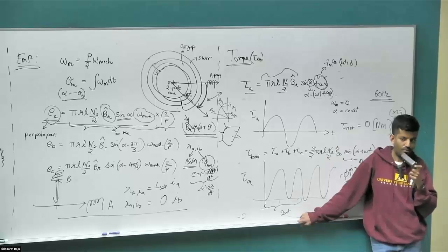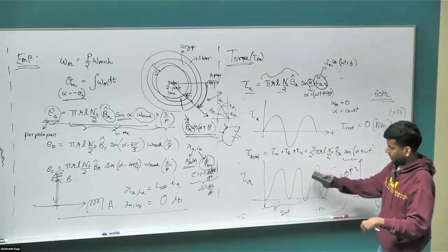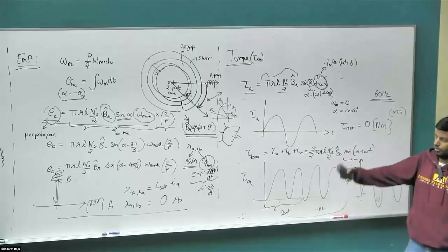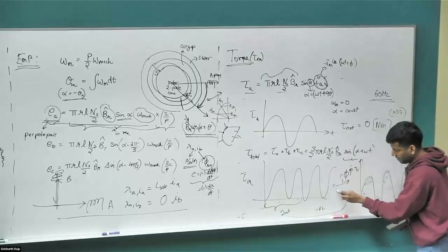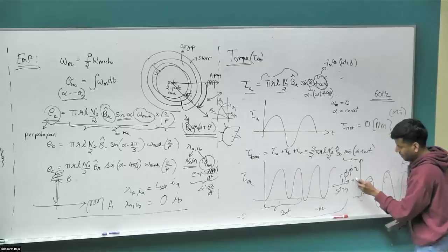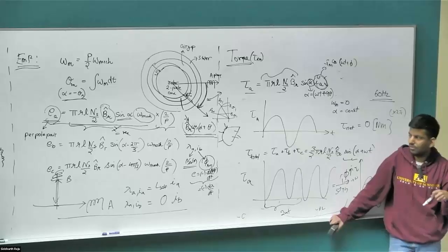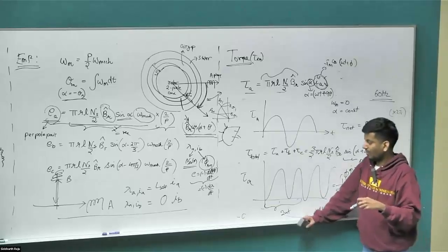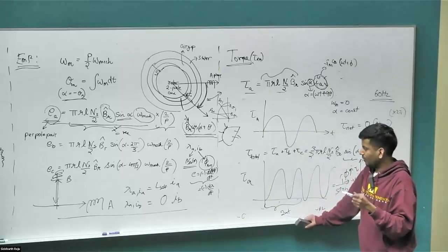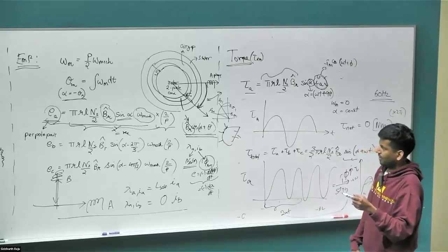Torque would oscillate because of this oscillation that we have there. This is then going to go into our transfer function 1 by Js plus b to create the speed omega. And this oscillation is then going to cause oscillation in your speed, which is going to become very inefficient and quite loud.